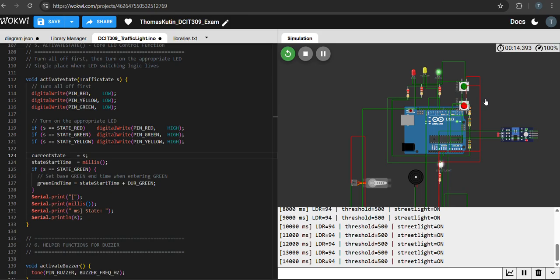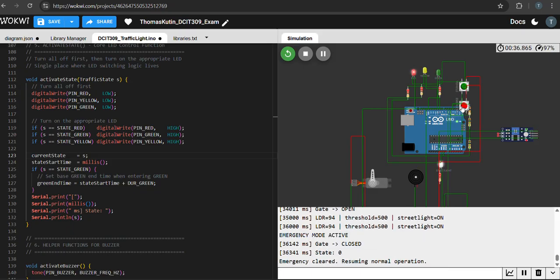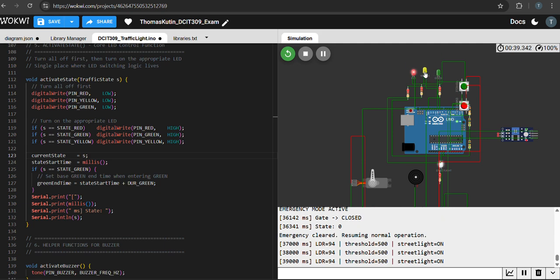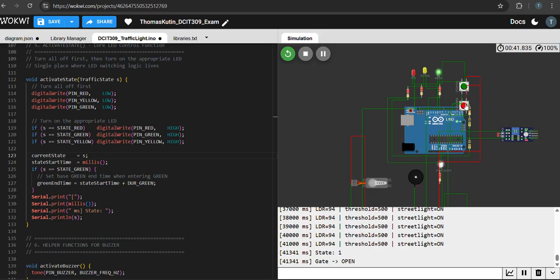So now the second scenario is to check whether the vehicle detection stops when the emergency button has been turned on. So let's try that one. Okay, so as you can see, it skipped yellow and went back to red because the emergency came on. You understand? So that means it works regardless. So let's wait for it to be green again, and you observe that again.